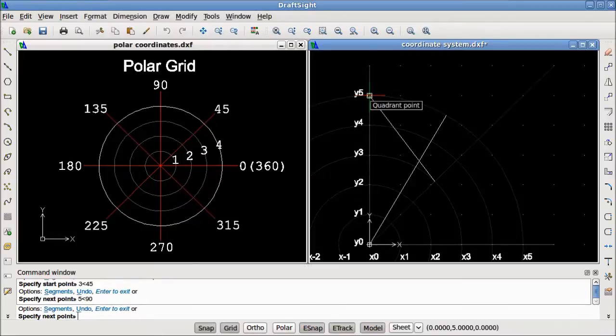Dimensions are given from point A to point B, then from point B to point C, with each point relative to the previous. You probably do not receive dimensions that are measurements from an origin to point A, from the same origin to point B, then to point C, and so on. To specify to DraftSight that we desire to use relative coordinates, we simply need to add an ampersand or @ sign to the beginning of the coordinates that we enter into the command window.